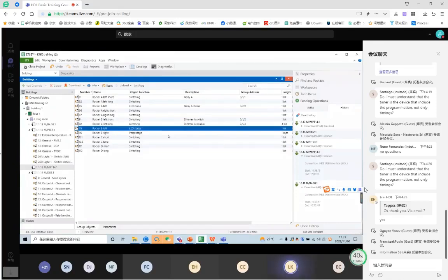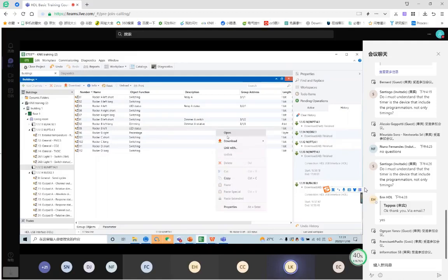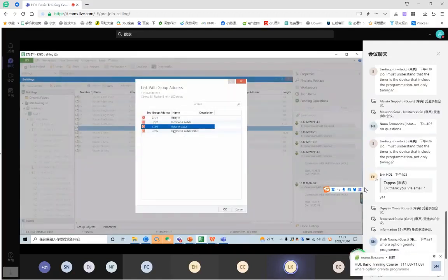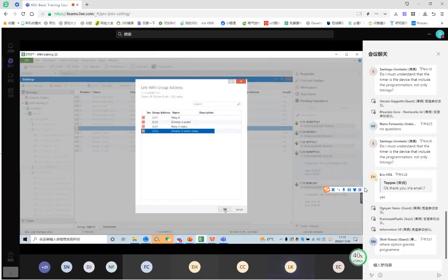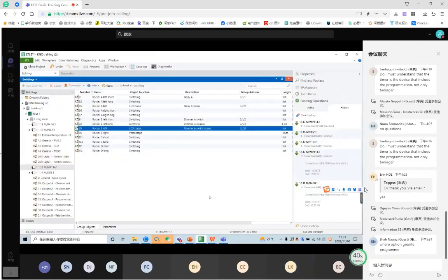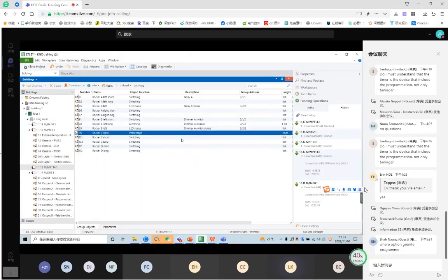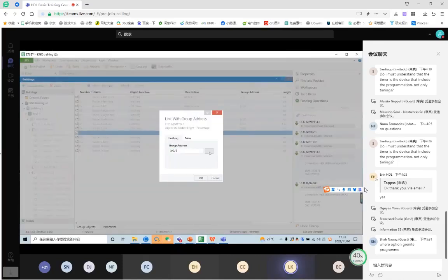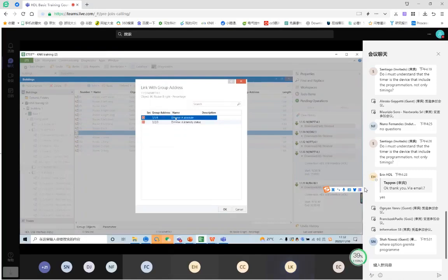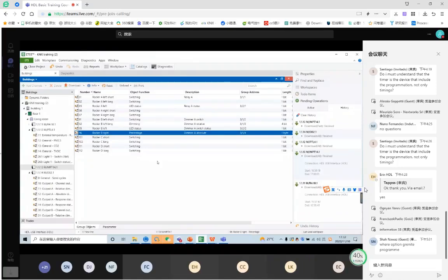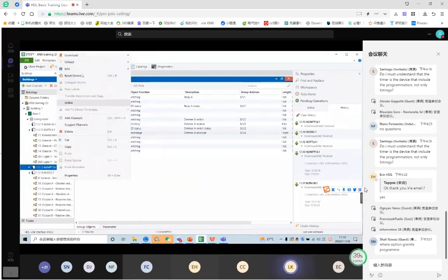Next is the LED status. We get the status from the dimming channel. And next, I want to control the percentage of the channel A. So dimmer A absolute. And then I should download the data to the DLP panel.